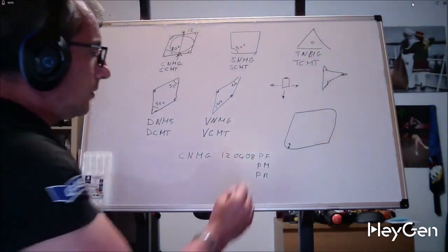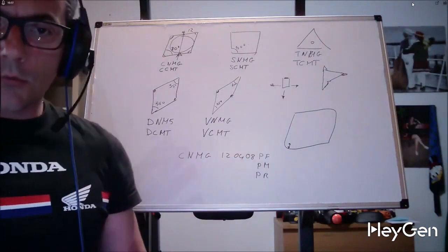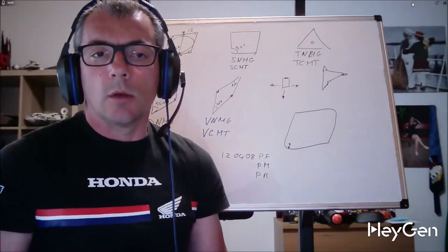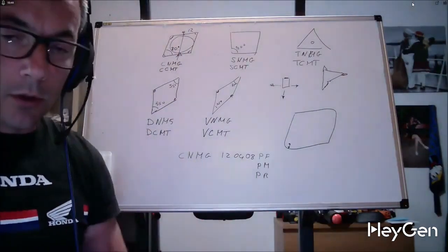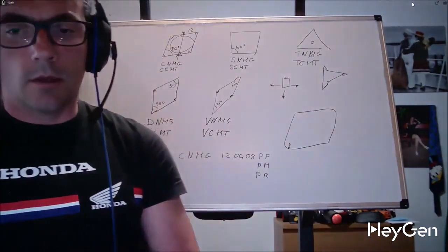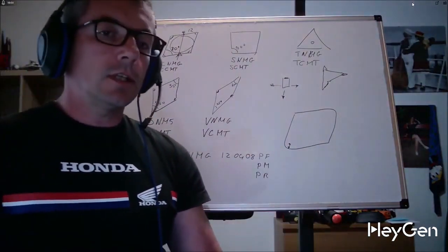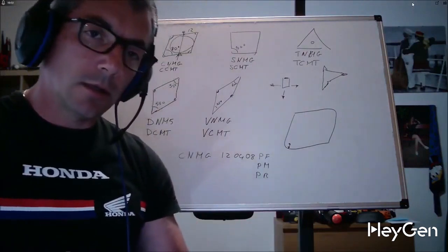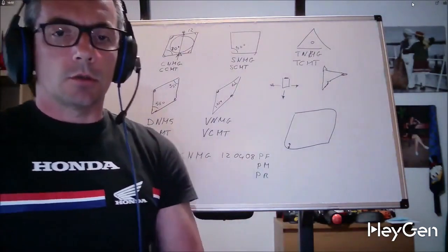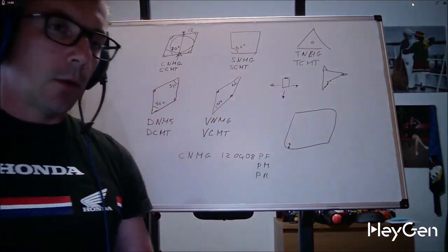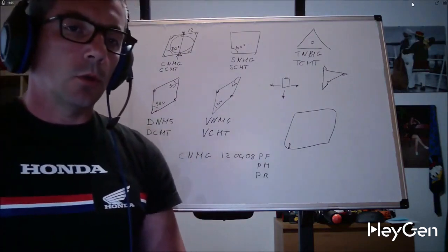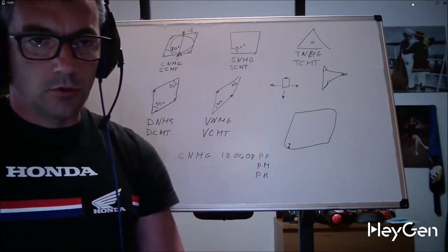Know that not everyone has been in workshops, and I asked for an insert for cast iron, and they told me that they only look at the shape. It's not that we use just any material. In fact, every material, and even every application, has its own insert. There is no absolute best insert, because the machine can also make a difference. However, we need to try to optimize the insert for the processing we are going to do. And here, guys, only experience is required.